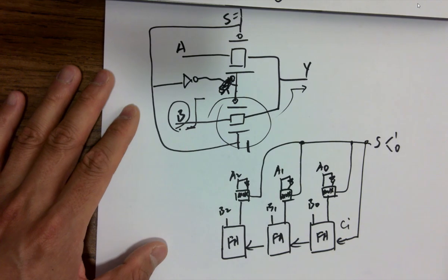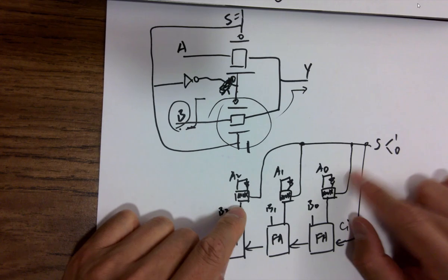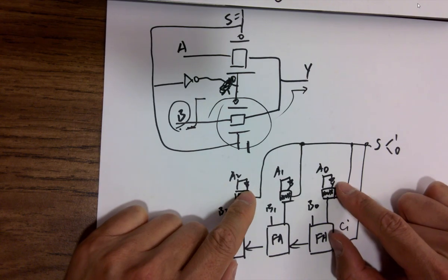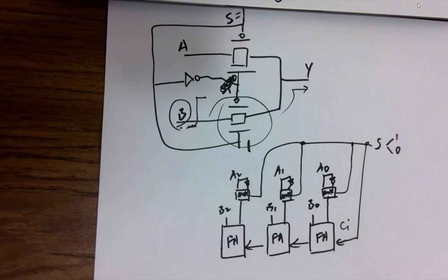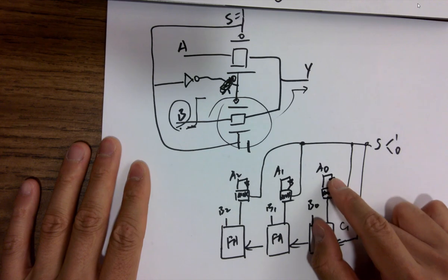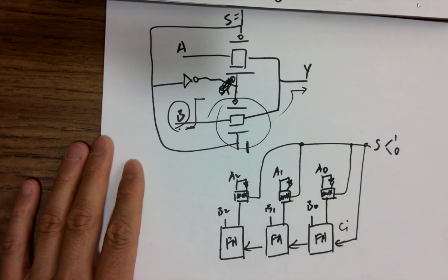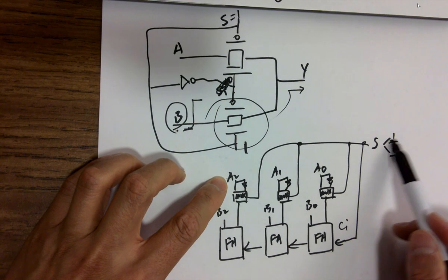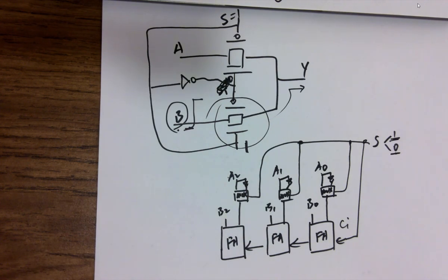But you want to make sure that when S is 1, which one are you picking up as an input for the mux? No, A bar, right? Yeah, A bar. So that's how, depending on your design, you have to put it into a certain input to make that happen. So this will be the first input in that case, because 0 will pick up the first input, and 1 will pick up the second input, which is the inverted one. So you can definitely use the mux to design a subtractor, adder subtractor as well.